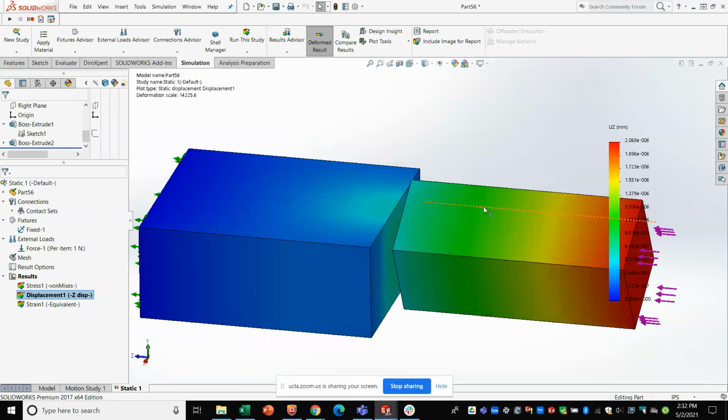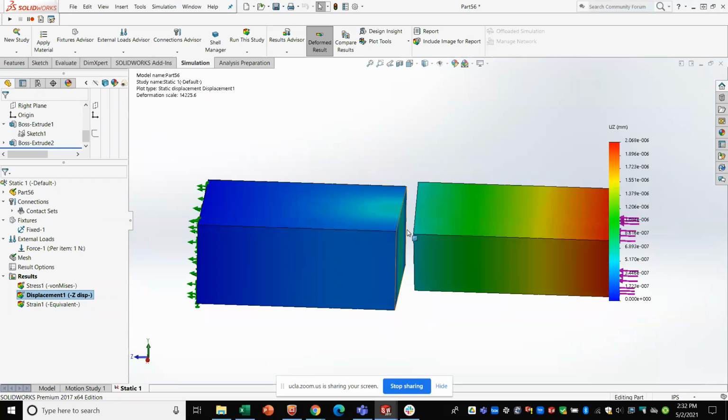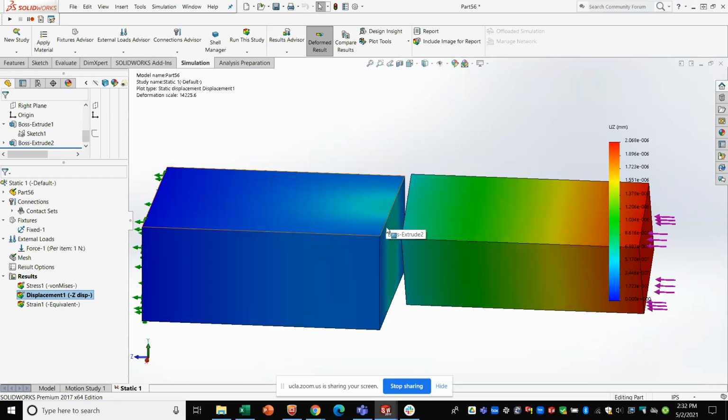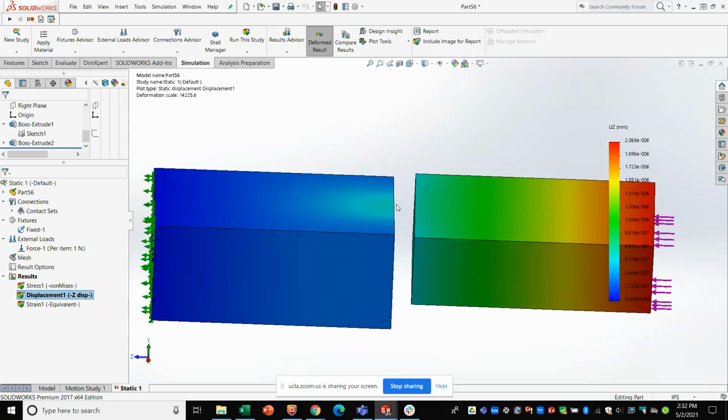Okay. If you recall, when there actually was a gap, but I had the gap option disabled, the part on the right actually did move the entire distance of the gap until it touched. When I have the gap option enabled, it's basically telling the computer, offset those virtual triangles, those triangle sensing elements, we'll call them, until they touch.